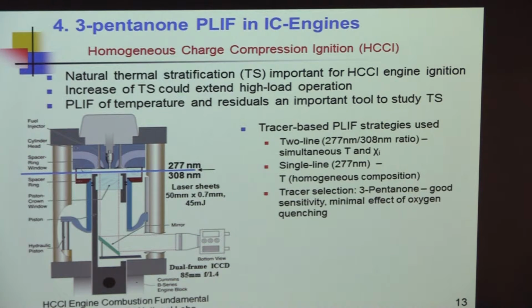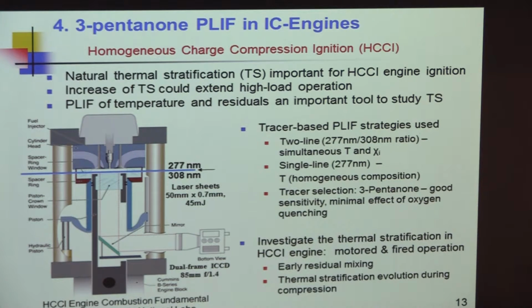He used 3-pentanone. Good sensitivity, minimal effect of oxygen. What was he interested in? In HCCI engines, they're very interested in the thermal stratification because that temperature controls the ignition. And they did this both in motored, which means non-combusting, and fired operation. They were looking at the early mixing and the thermal stratification. So they wanted to measure very small changes in temperature and mixing.